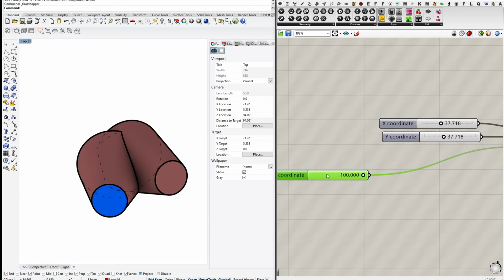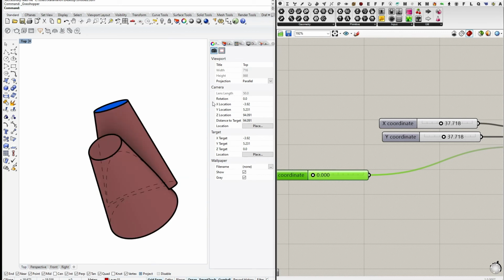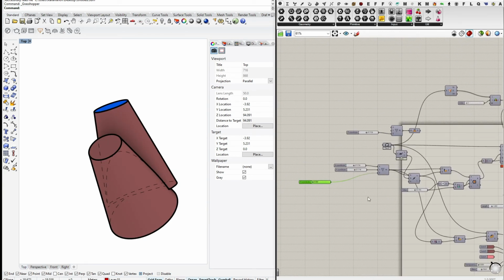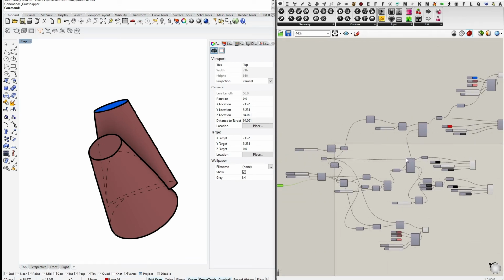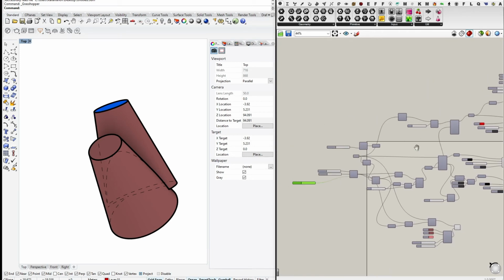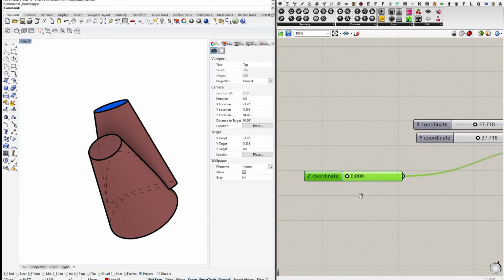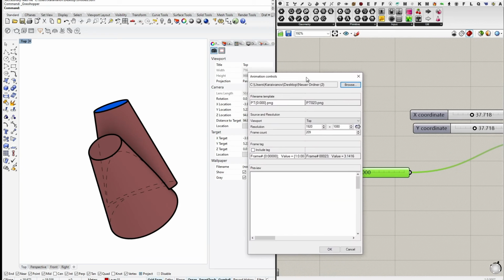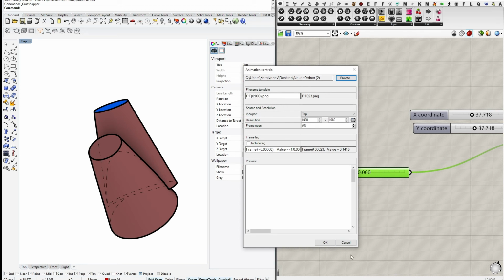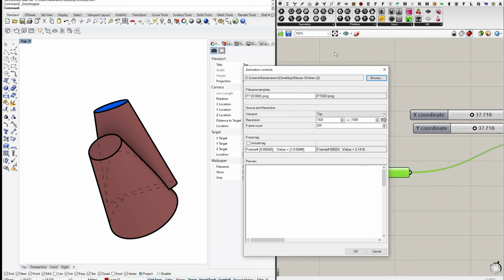This is already like very vertically from the top. But as you can see, it works actually quite smooth, like it's for generating the make2D. If you have a lot of geometry, each iteration might take some time, but for now, this works actually quite well. And so how to animate the slider, how to generate actually the single frames that you later can use for editing a video. So if you right-click on your slider and you go to Animate, you will have a small window popping up that essentially sets up your slider animation.